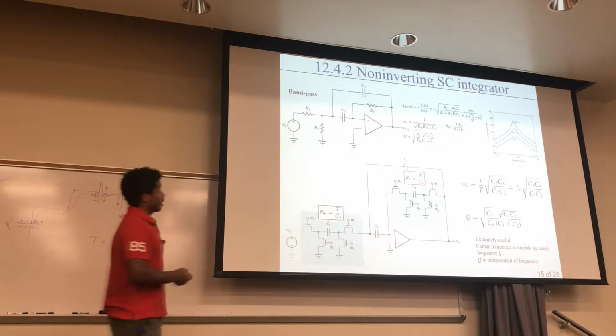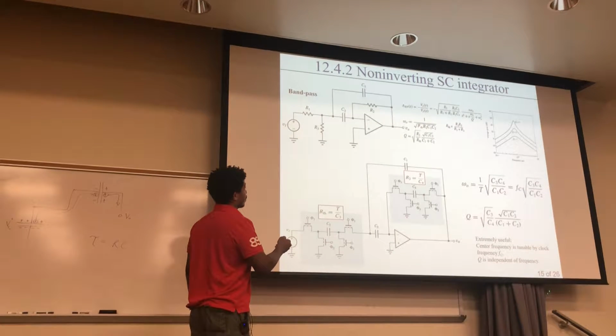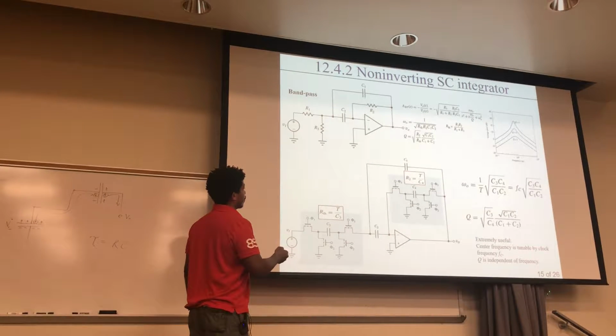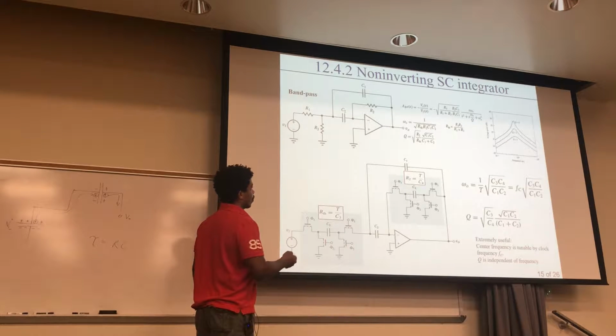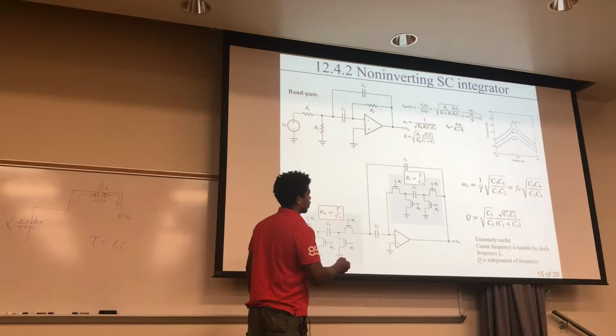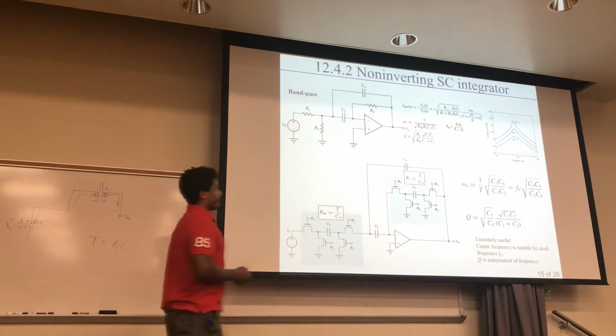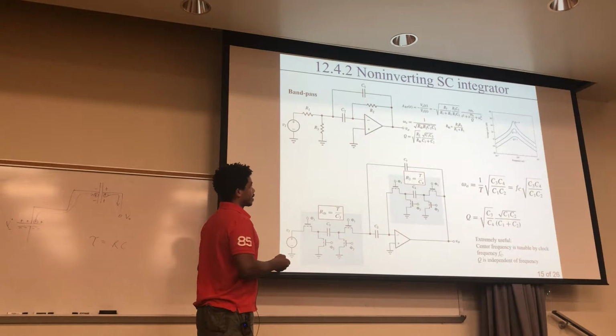Okay, so that means that we could take these equations and just replace R Thev and R2 with these two things right here. And if we do that, this cutoff frequency now looks like this. Okay, and you can see the period here, the sampling frequency right there, and here's the quality factor. Now, what's really nice about this is that we can change the resistance, right?